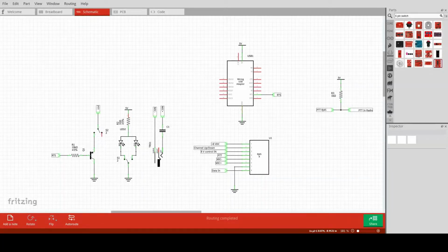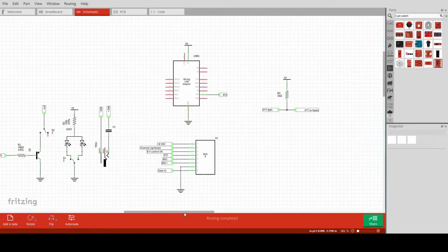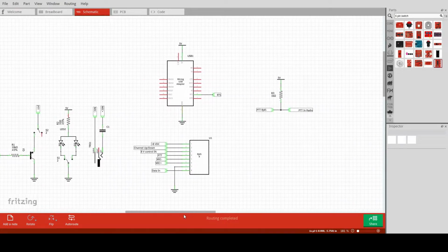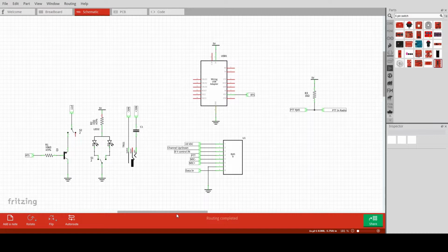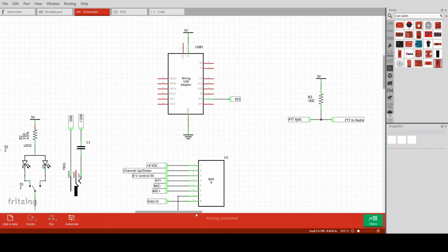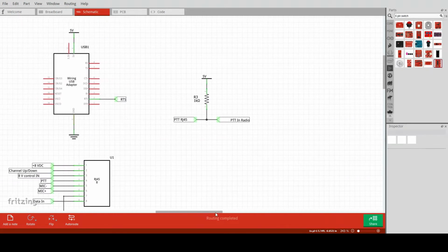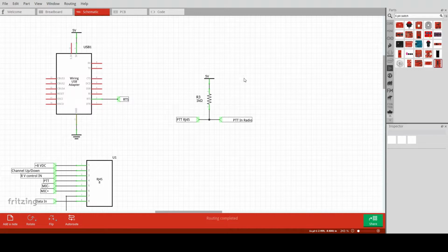So after I took those measurements on my radio, I sat down and drew a small schematic. It was first on paper, but I wanted to put it over to here so I could have a better idea. I decided from measuring what I measured between the PTT and the ground that inside the radio had to be something like this. You'd have a pull-up resistor.